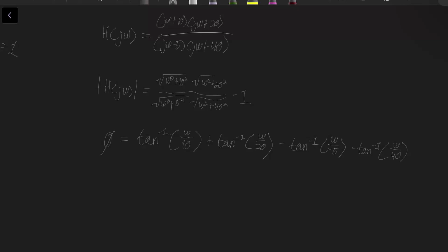When you write this out in your gain equation, you would have a 20 log base 10 of -1 term, and this would become complex. So it would get funky. Don't worry too much about that. It's beyond the scope of the class. We're not going to ask you that, obviously, but just so you have it in the back of your head. In general, it's just a rule: add the DC gain to the magnitude equation.